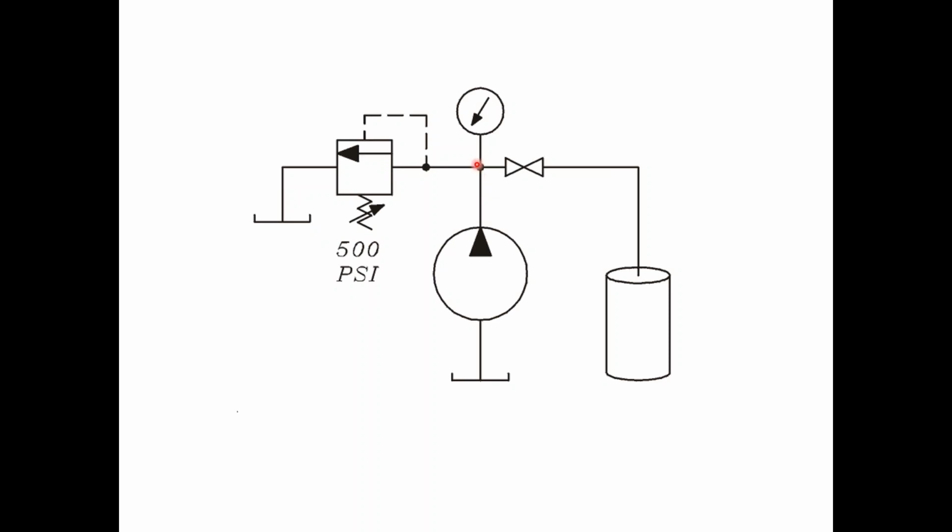So that's the resistance that we have in this direction. That has to be overcome in order for oil to pass this way. Okay? Now, in the other direction, we get to a symbol that looks kind of like a bow tie. This is a symbol for a manual valve. Could be a hand valve, typically a ball valve or a gate valve or a butterfly valve. They can be open, they can be closed. This one's open. We illustrate that by showing it not filled in. So if it's properly sized, it doesn't add any resistance to the system.